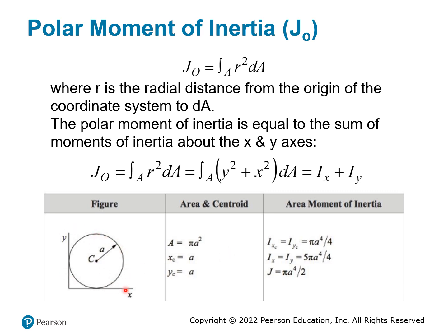So if you have a circular shape, the centroid is right at the center of the circle. You can find Ix, you can find Iy, and they are all equal to this because they are symmetric. But if you want to find the Ix that refers to this axis, not this axis, okay? This part here is with respect to the centroid of the circle. This one here represents this one right here, so it will be different. The other one is the polar moment of inertia, which is this one, and it is with respect to this point right here.